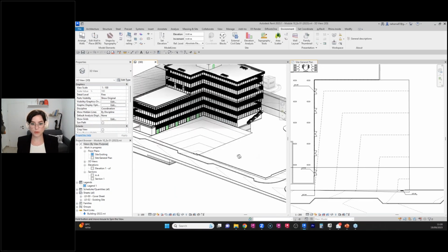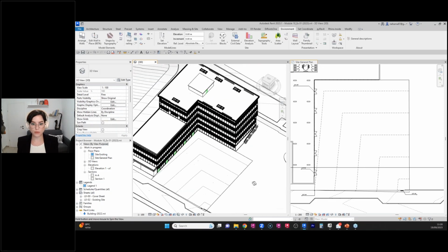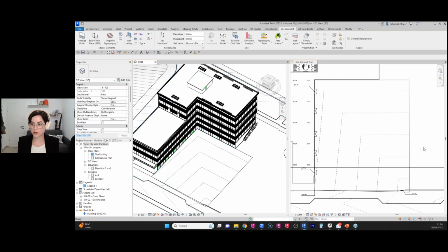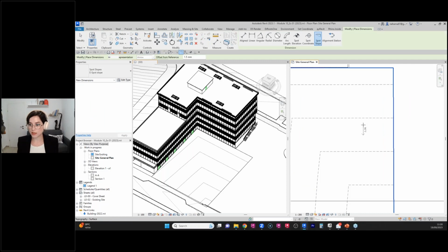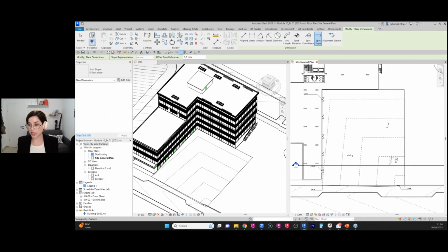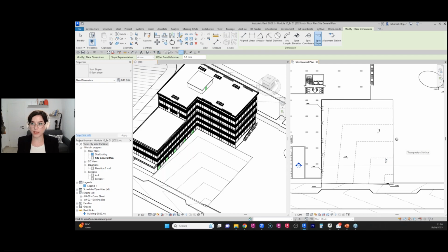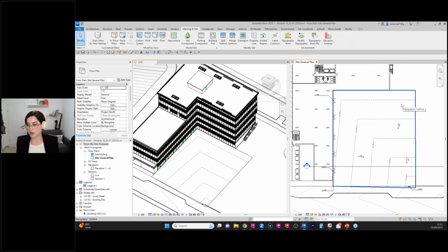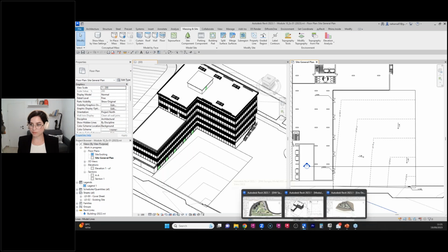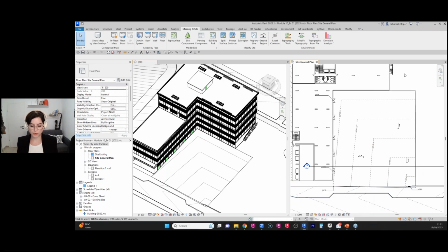And that's one of my favorite examples of how you can really design a complete plaza without calculating any point. And again, if you're moving from CAD to Revit, then Revit's native ability to show you the slope value is just a game changer from the standard CAD workflows. And then we can go to the Massing & Site option over here and just get the labels on these contours. So that's the first example of how we are working with the topography tools.